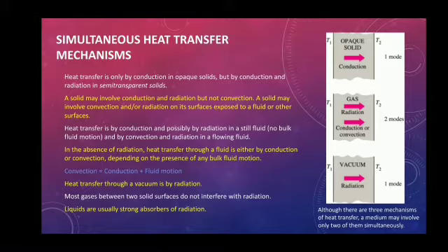Heat transfer is only by conduction in an opaque solid, but by conduction and radiation in a semi-transparent solid. A solid may involve conduction and radiation but not convection. A solid may involve convection and radiation on the surface exposed to a fluid or other surface. Heat transfer is by conduction and possibly by radiation in a still fluid, with no fluid motion, and by convection and radiation in a flowing fluid.